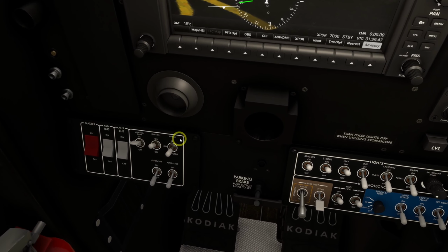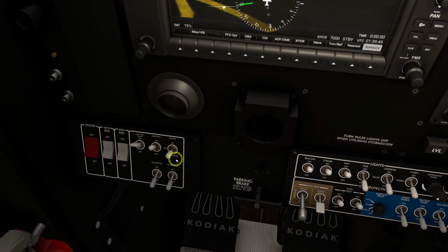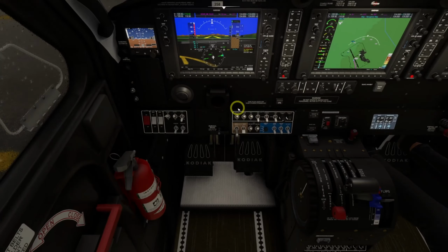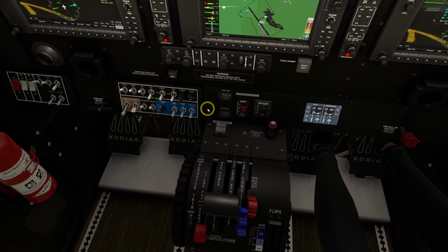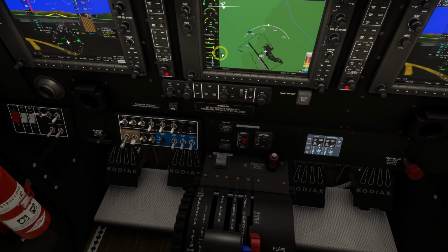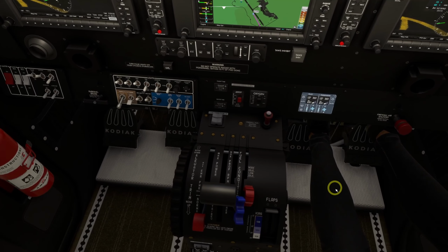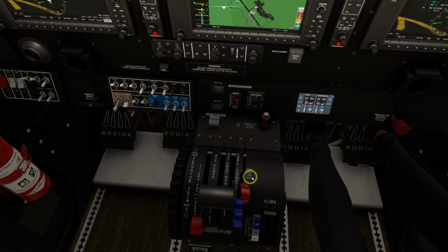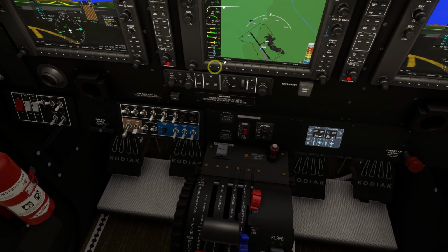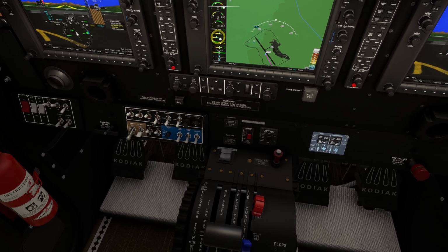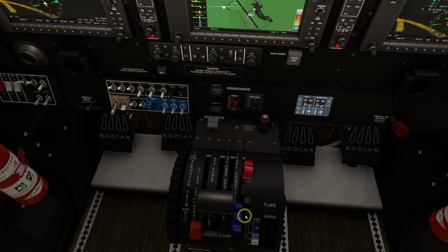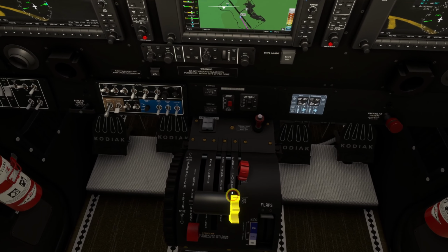Ignition can go on. This is the first start of this aircraft, so I'm going to go low motor. Come back. Go to control 2, so I can just see everything on my gauges. Looking good, so I'm going to increase my fuel condition lever to low idle. Just a little touch on my controller. And I'm happy now. I'm going to push my RPM just full.